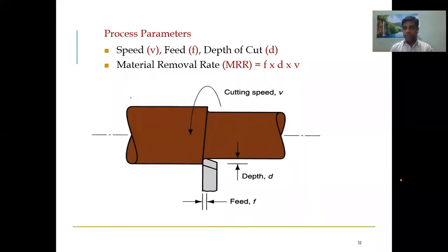So then coming to the other parameters which we need to find in a cutting or machining process. I told you initially that 3 parameters are very important other than the rake angle, the geometry of the cutting tool, that we give during manufacturing or machining processes. First thing is speed. For example, you see here, this is a typical lathe machine. The workpiece inserted is rotating at a particular speed, right? This speed at which your workpiece is rotating is called the speed of cutting.